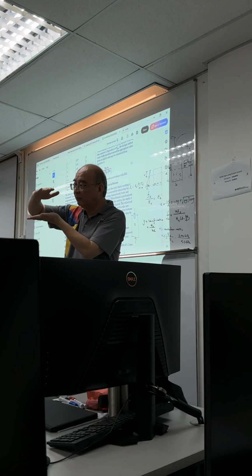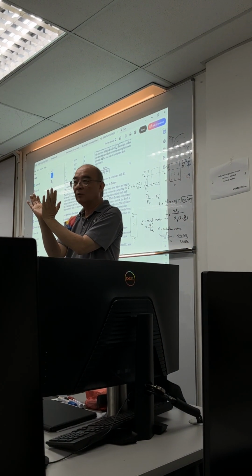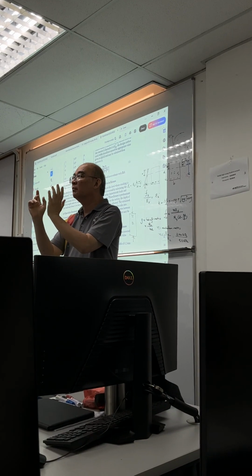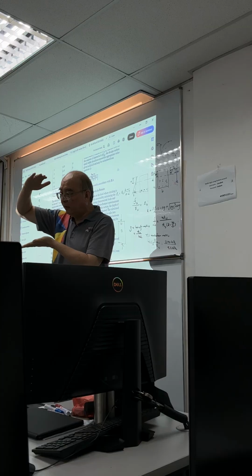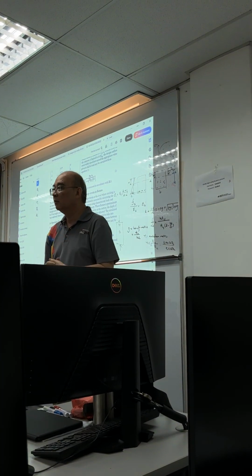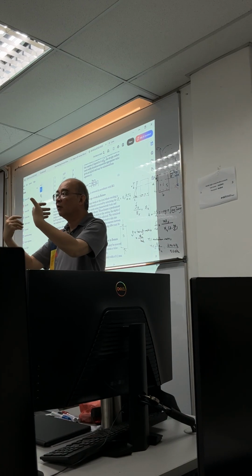Because when you press something, this is going to bulge out. Correct, right? Why does it bulge out? Because remember in your mechanics of materials, we talk about the Poisson ratio. When we have an axial, we will have a lateral. And the lateral is actually causing the cracks.